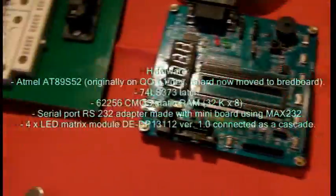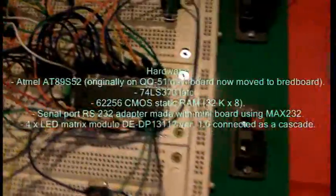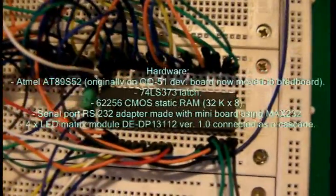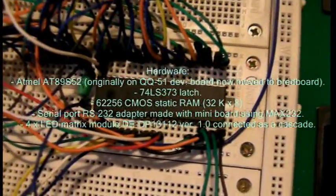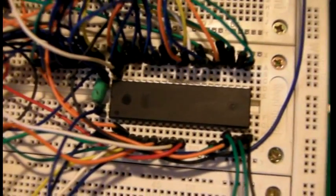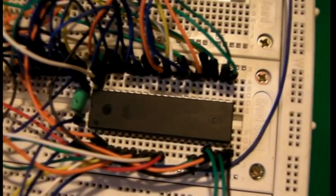So let's go into the hardware specifications. The heart of the controller is the ATMEL 89S52, an 8051 compatible computer on chip. It has 8 kilobytes of onboard flash programmable memory. This is ROM. This is where the program is stored, and 8 kilobytes should be more than enough for my needs, for just the code.